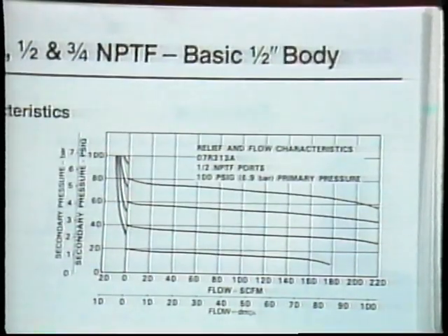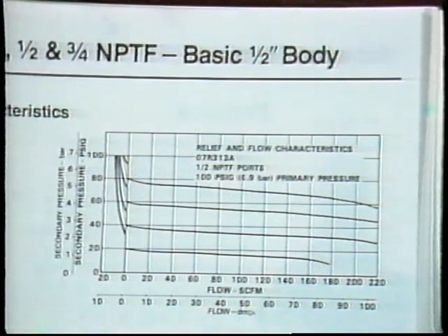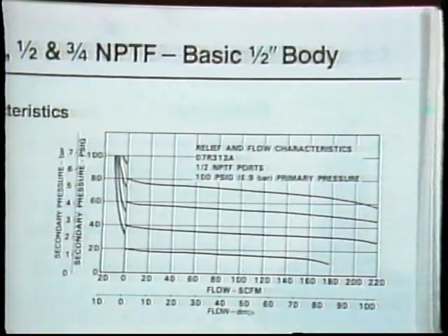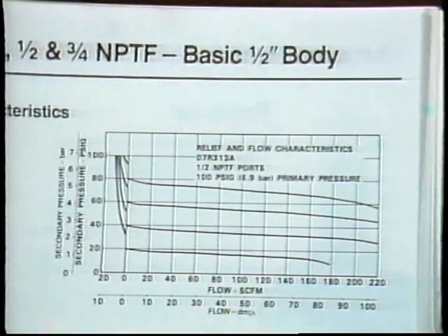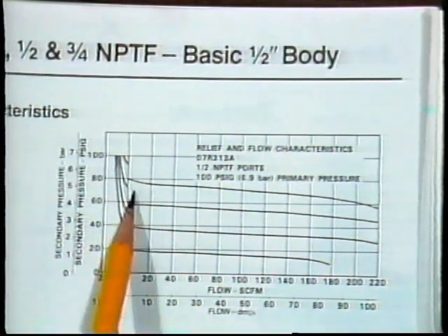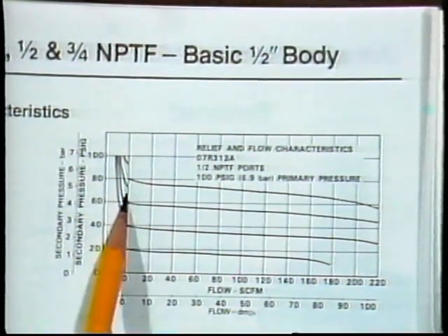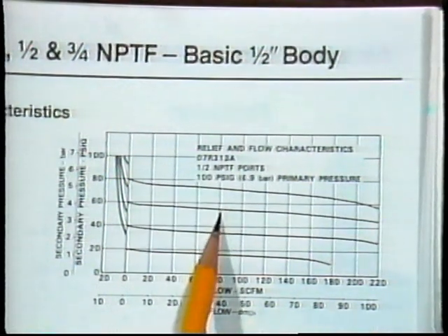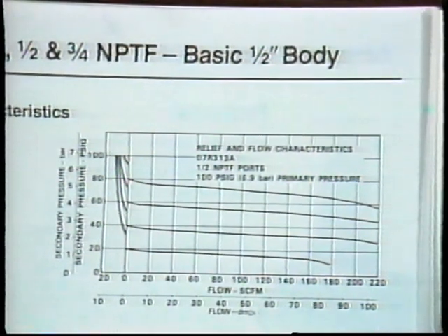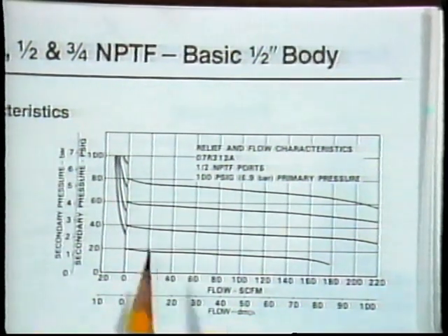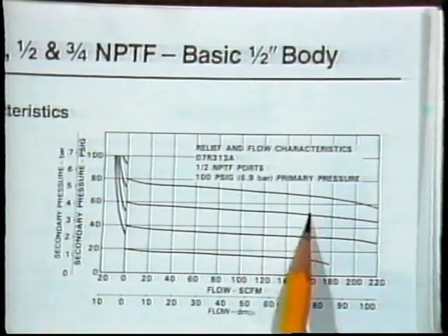In all pressure regulators, as the flow is increased, the pressure on the secondary, or what is called the reduced pressure side, drops slightly below the no-flow pressure setting. This difference between no-flow pressure and actual operating pressure is called regulator droop. For this reason, designers should select a regulator that has minimum droop in the normal operating range of a system.